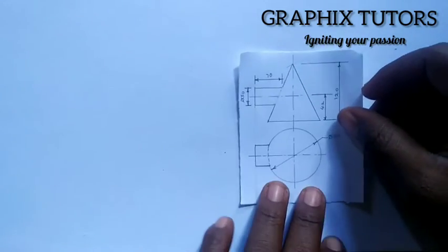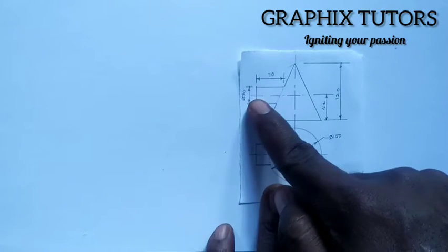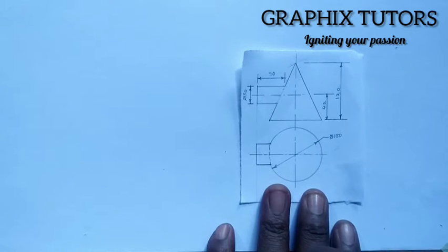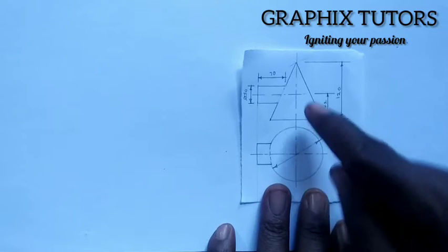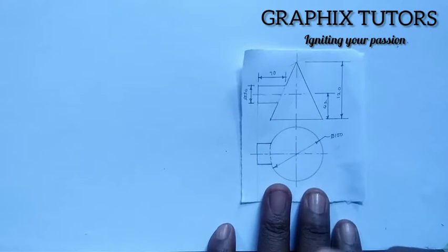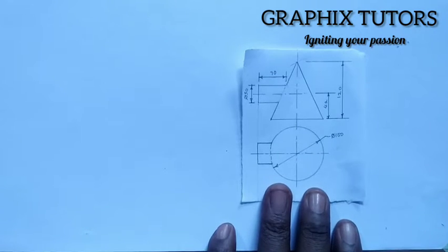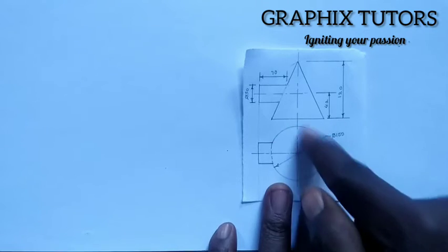Today we want to solve another exercise on interpenetration, but in this case we'll be talking about a rectangular pipe and a triangular pipe that is being joined together. So we want to see the interpenetrating arc of this figure, and we want to also see the effect of it in the plan. So the first thing you draw is your plan first. So let's start from drawing the plan.